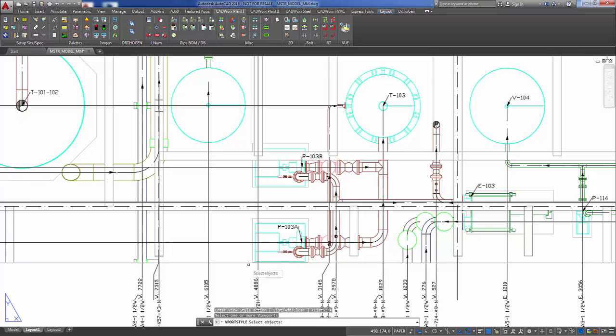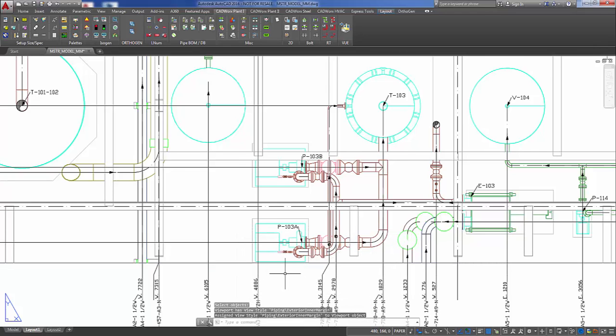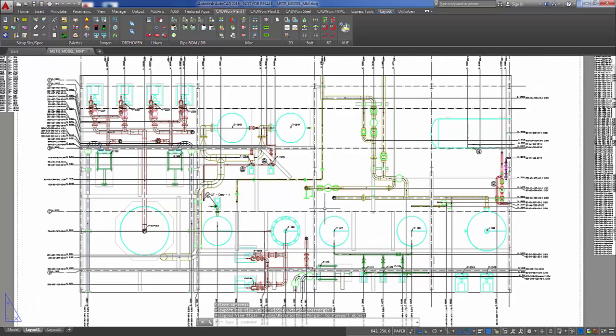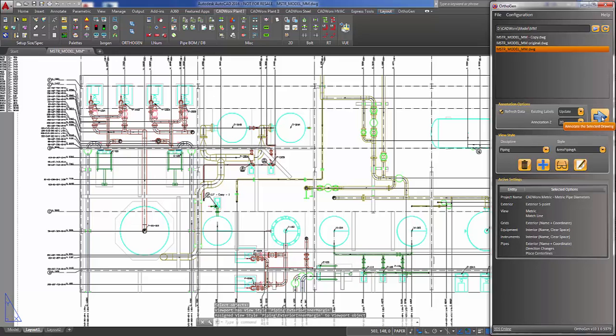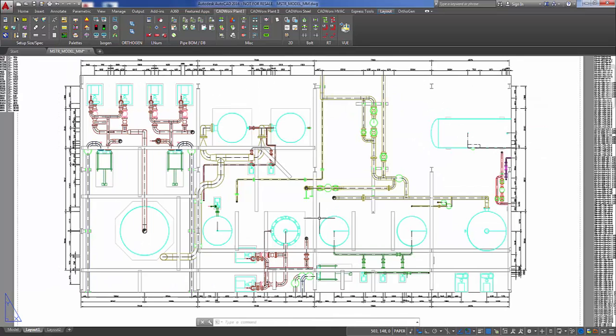You select add, you select the viewport, accept it, and then you just navigate out to the style that you want to add. I'm going to add this exterior inner margin as a style, and permanently it's now attached to the viewport as X data. So if I update this now, even though it says area piping 1, you should see just the dimensions. This was exterior dimensions. That's the style where it only put the exterior dimensions.